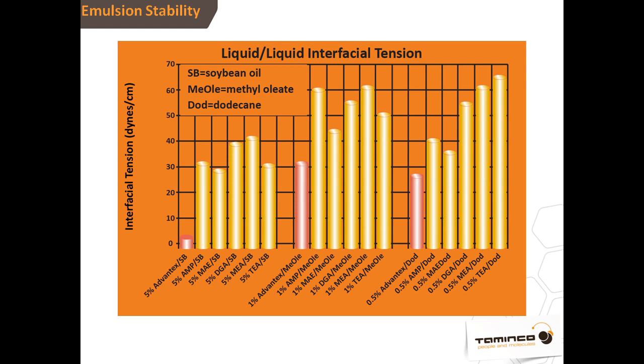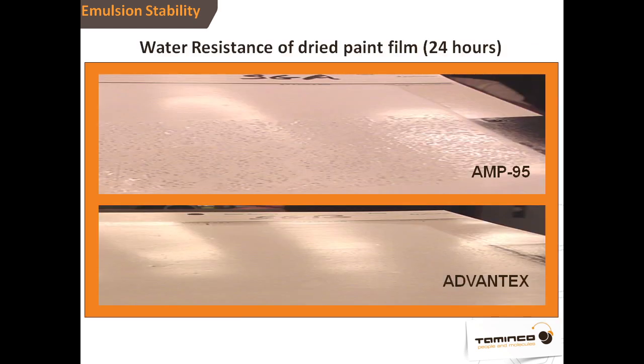So we did do some water resistance experiments where we compared mid-range HLB alkanolamines to higher HLB alkanolamines with higher vapor pressure. The expectation in a comparison like this would be that the lighter alkanolamine would evaporate more rapidly and therefore would render the film less water sensitive. But we saw in the first 24 hours the opposite effect.